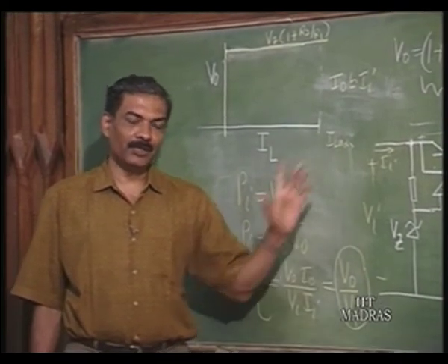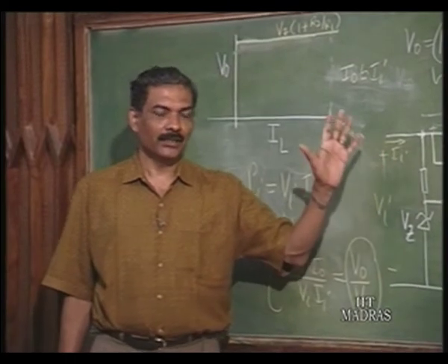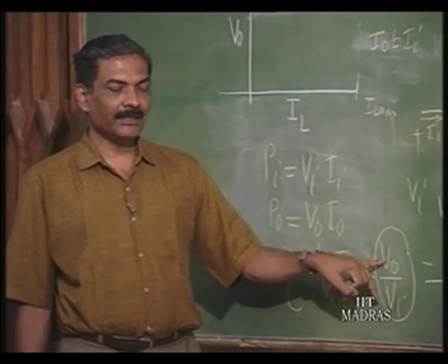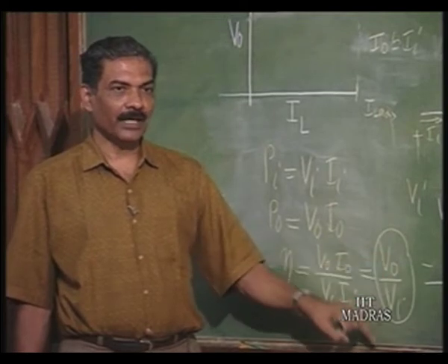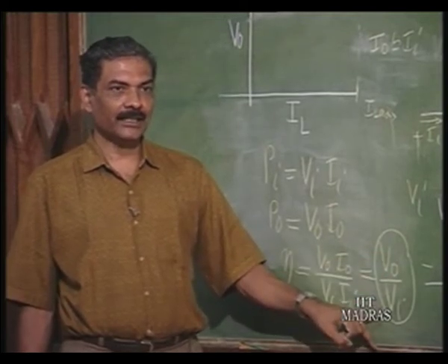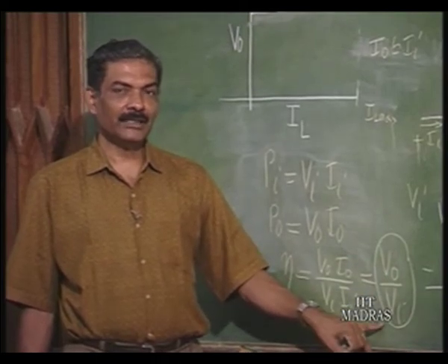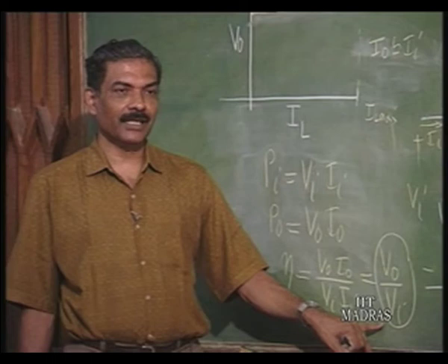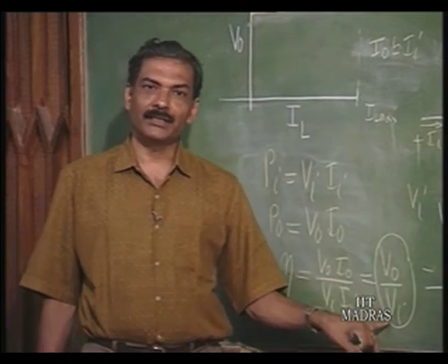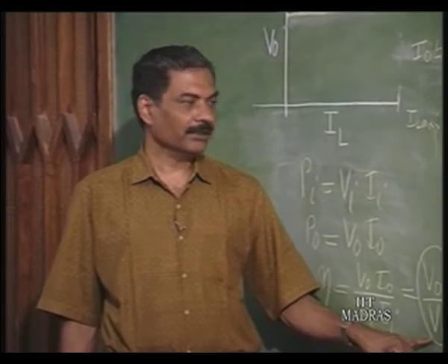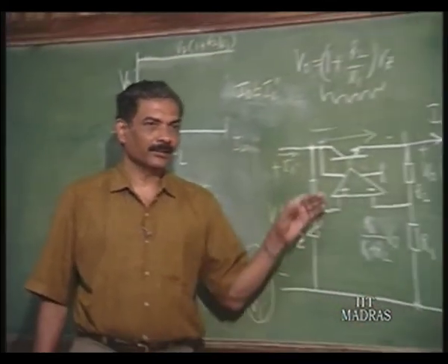At any given time, input voltage has to be greater than output voltage. So, the best efficiency I get is 4 by 5 and the worst efficiency I get is 4 by 10. So, it might just get stuck at V I equal to 10 and I will be operating only at the worst efficiency situation of about 40%. The rest of it is dissipated in the transistor.